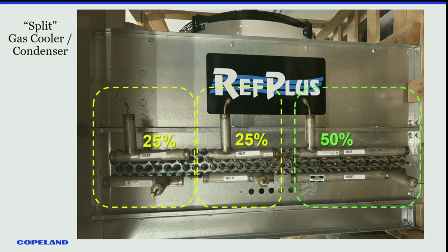What we're starting to hear more about, this was a gas cooler we had designed for our own training center in Canada. Because it's in Canada, we wanted to have split condensing. And split condensing is not something that's used a lot here in CO2 yet. In conversations with our Australian colleagues, because it gets really hot in parts of Australia, they're starting to install split gas coolers, not for the cold, for the heat. So it can handle those 45 degrees Celsius days, but when 80% of the other hours are not 45 degrees or more around 30, then they can split the gas cooler and manage the pressures better. We wanted 3 sections, only because we wanted to highlight it in our training center in Canada. But that's something that I think conversations are starting to build again in North America.